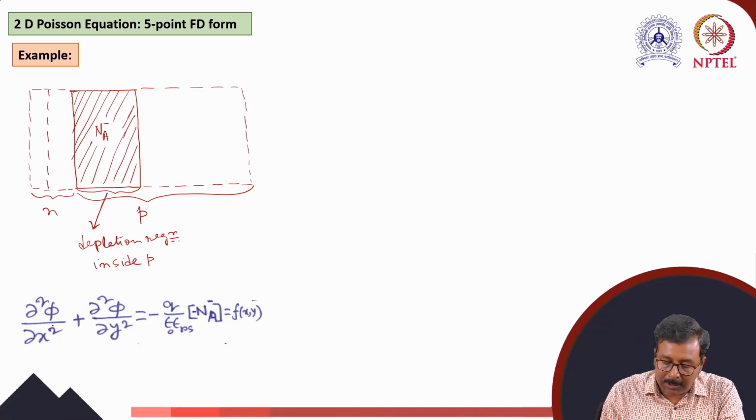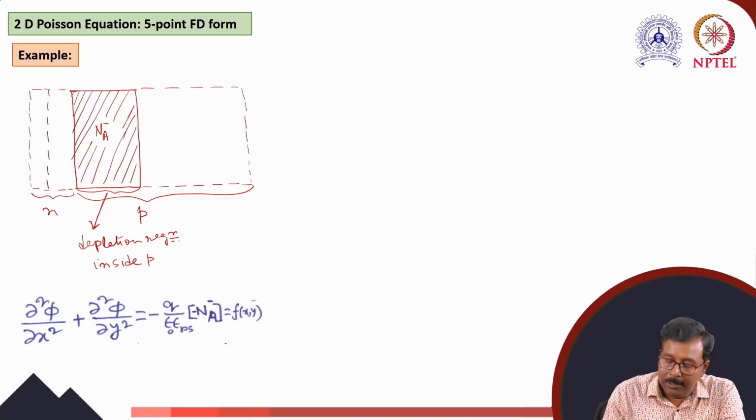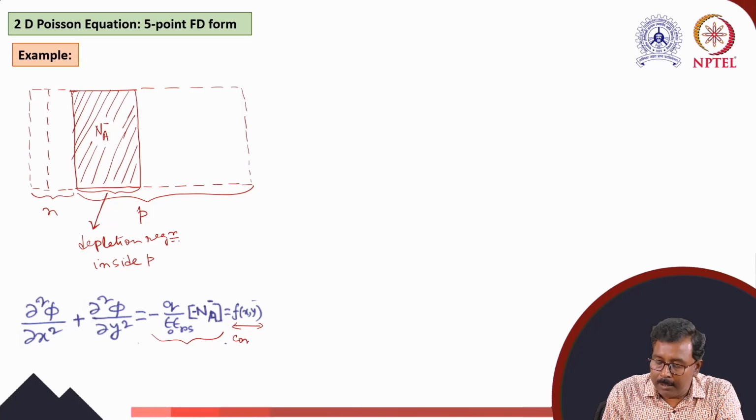So the Poisson equation, del square phi del x square plus del square phi del y square, will be equal to minus q by epsilon, that is epsilon 0 into epsilon rs, times minus Na, because we are considering only the acceptor ions present. This may be written as f of xy, but in this case this is a constant.